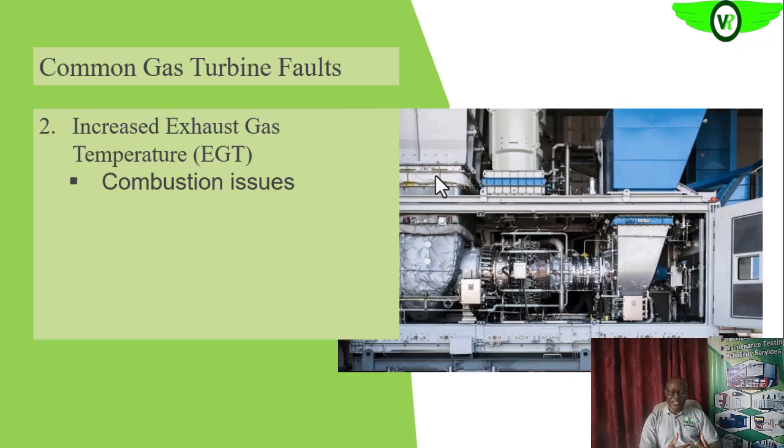Then it is also possible that the fuel we are having is not of the right specification, so the combustion effect, or the rate at which it is burning, is not as desired. Are we getting it? It can also affect the energy contained in the combustion product. So issues with the combustion chamber or the combustor can affect what we are having at our exhaust gas.